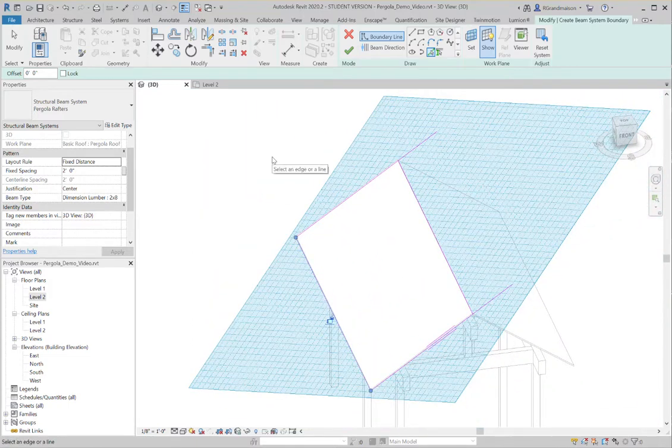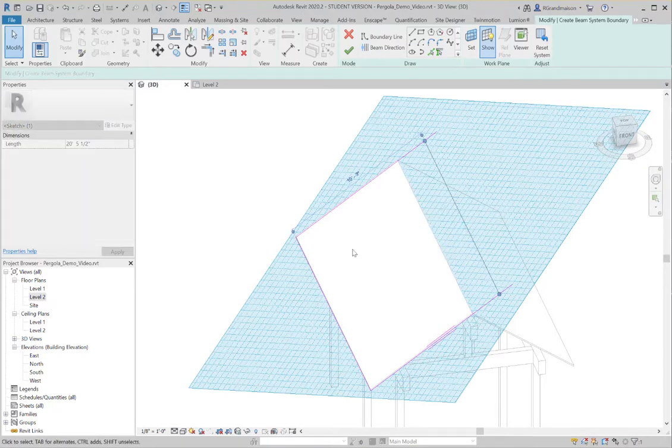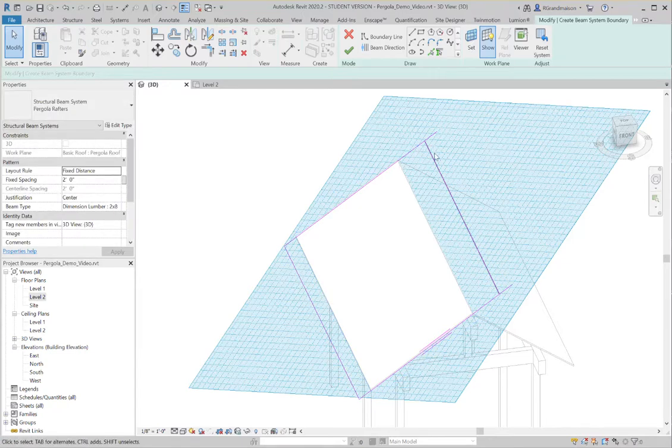Now I'm going to do something a little bit sneaky here. I want these rafters to extend out past my ridge beam. So I'm actually going to take this line here and I'm actually going to drag it up about like this. And because I might want to have some exposed rafter tail on these, I'm going to drag this downwards as well. It's a sketch, so I have to clean these up. So I'll issue the TR alias to allow me to corner trim these two lines together like that. These ones here are fine. I can tell by looking at them. So I know I'm okay.